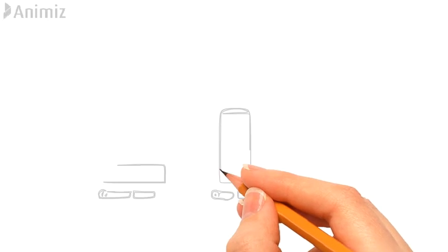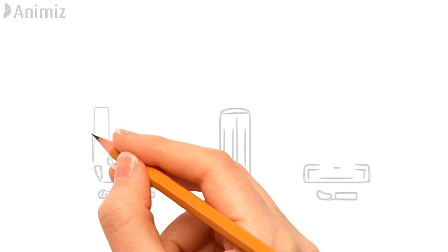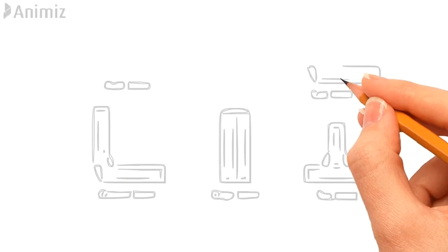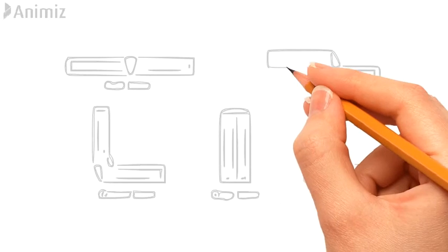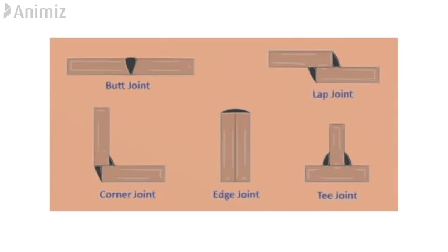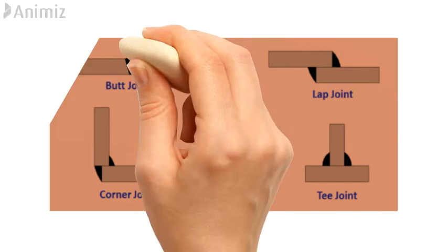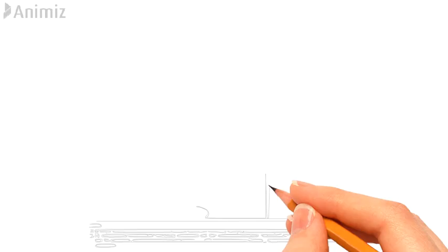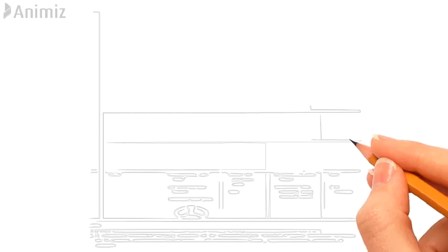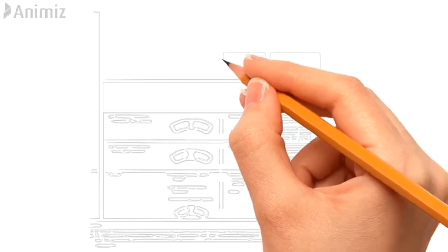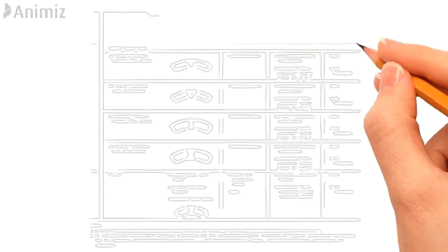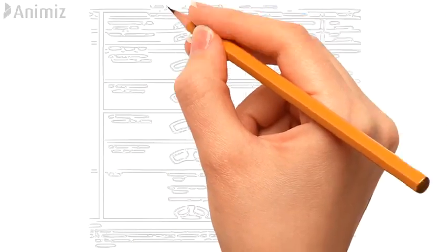Basically, welding joint efficiency is one of the important factors for calculation of the required metal sheet thickness for pressure vessel design at intended pressure. And with time, welding joint efficiency reduces due to the age of the vessel and corrosion. If you see the handbook from ASME, you will find that welding joint efficiency is considered between 0.65 to 1. 1 is considered for radiographic welding, and this joint efficiency also depends on operator skill. As welding joint efficiency reduces, MAWP of the vessel also reduces.